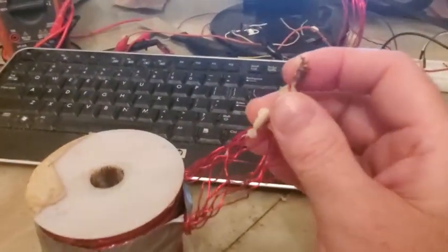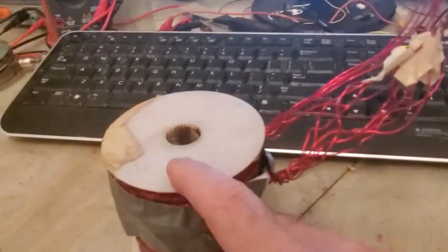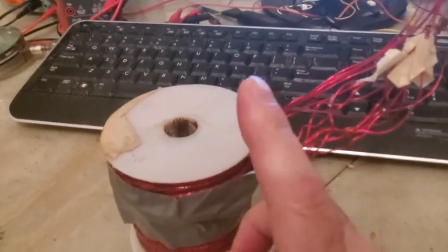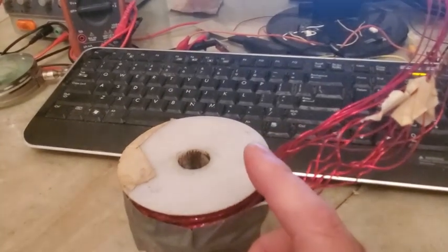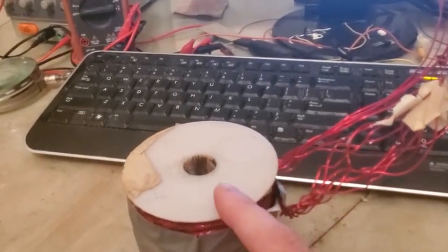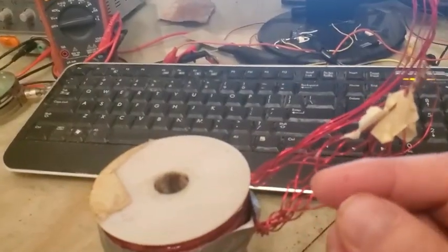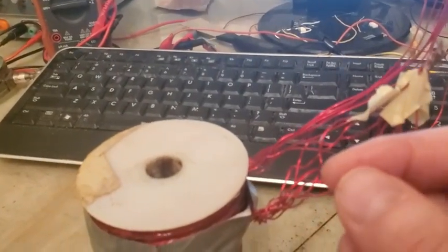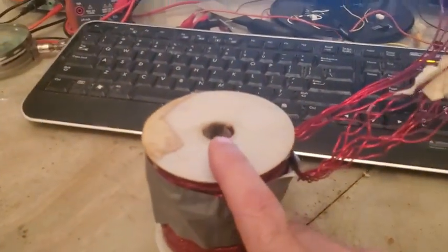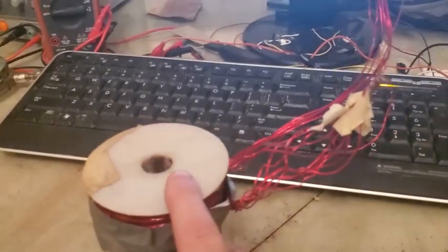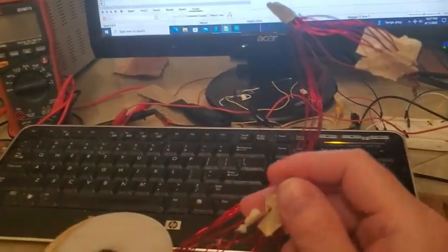So this wire is way thicker even than the 14 gauge. It has much lower resistance. I measured this coil, and it has something like 1 millihenry. I think that was probably on purpose. It's either between 0.2 or 0.4 ohms of resistance. So now that switch with 1 or 2 ohms of resistance is not going to cut it, because now you've got 5 or 10 times more resistance in your switch than you have in your actual coil.